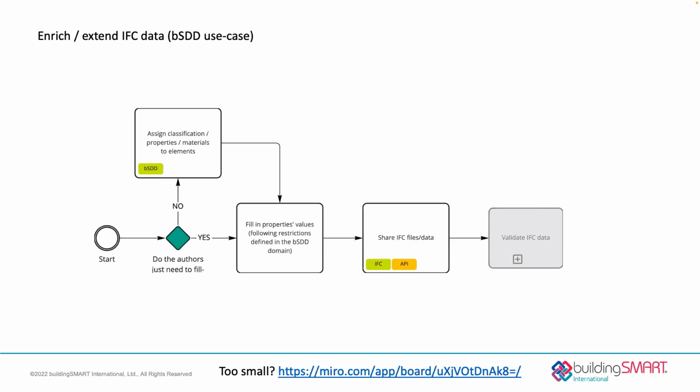I was going to ask the question, but it's a good point, because if it's Trimble Connect, I know the answer. So I was going to ask: is this modifying the IFC, or is this actually just extending externally? One of the things I'll talk about is that the Trimble Connect model is an entity component model, where in Trimble you're actually not editing the IFC, you're just making the associated link to these P sets that are added. So it's a good discussion topic as we look ahead: is that the right model, or is it actually cracking open the whole IFC file and trying to edit it directly, versus putting data next to it that has a very strong link to the entities?